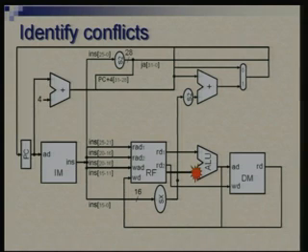This is one point of conflict, where add subtract instructions send one thing here, and the load store instruction try to send something else here. In one case we are adding two operands coming from register file, in other case we have one from register file, one is a constant coming from instruction. So, this is a point of conflict. This is another point of conflict in terms of what goes back to the register file. So, in arithmetic instructions, output of ALU goes back, in load instruction output of data memory goes back,